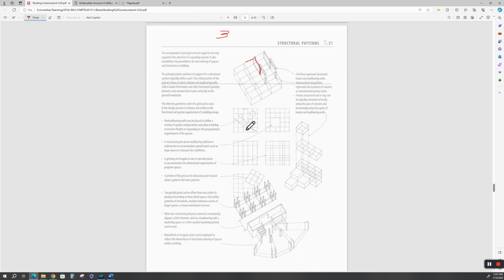If it's a residence, then you need to design the floor plan, and the floor plan will determine where the walls need to be and what walls are load bearing and what walls are not load bearing. They're just partition walls. If it's a commercial space, what are you going to be doing in this space? Is this a bunch of machinery? Well, if this is a big CNC machine in a little machine shop, we don't want a column right there. So again, what's the intent and purpose of the interior space? Balance has to take place.